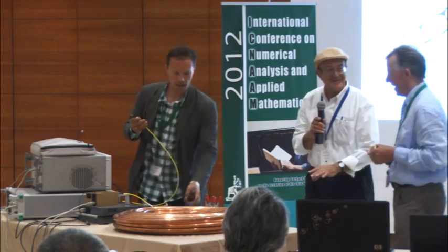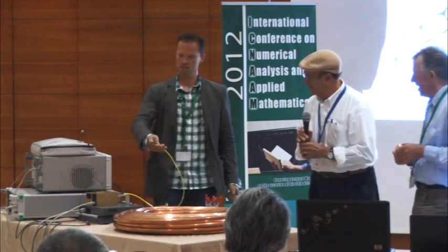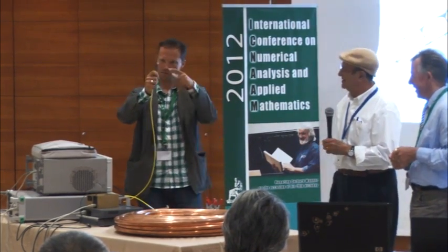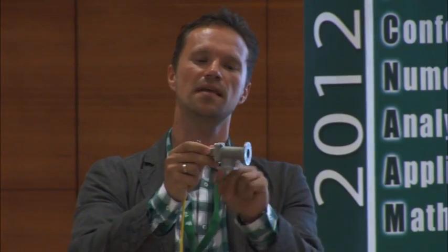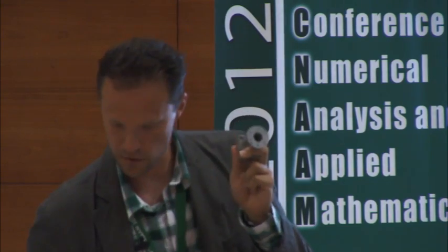So again, I'm going more into the details. So we have the cable. So here we have the result. We have the carrier and the signal modulated on top. That goes into this adapter. And you have to see it like that. The end of that cable works like an antenna. So it radiates the wave into the waveguide. So this is the waveguide that is able to transmit that frequency that I was just talking about.